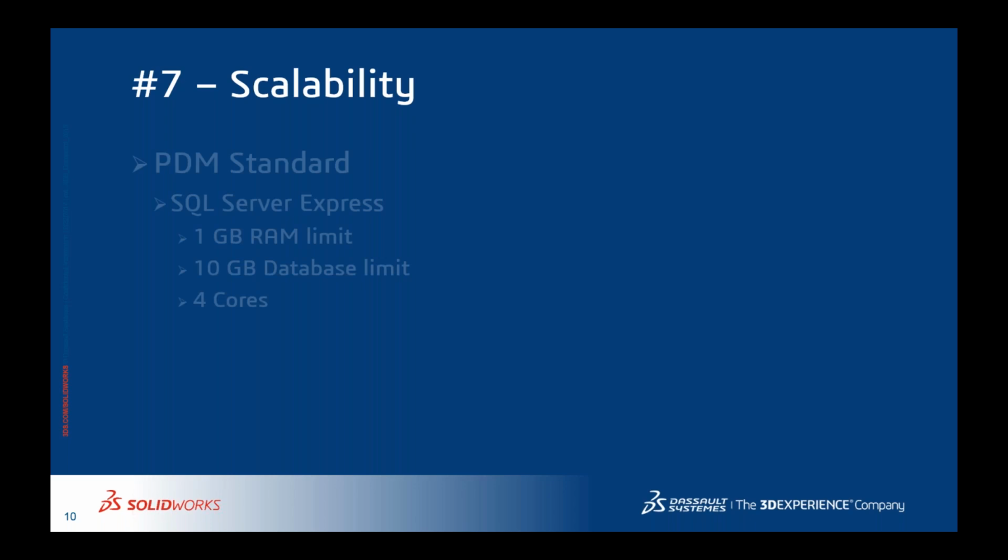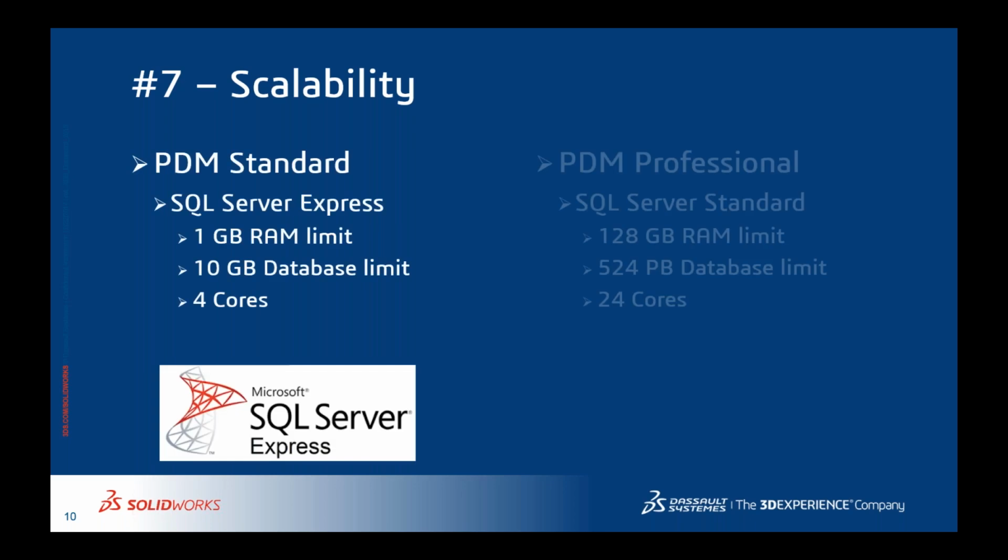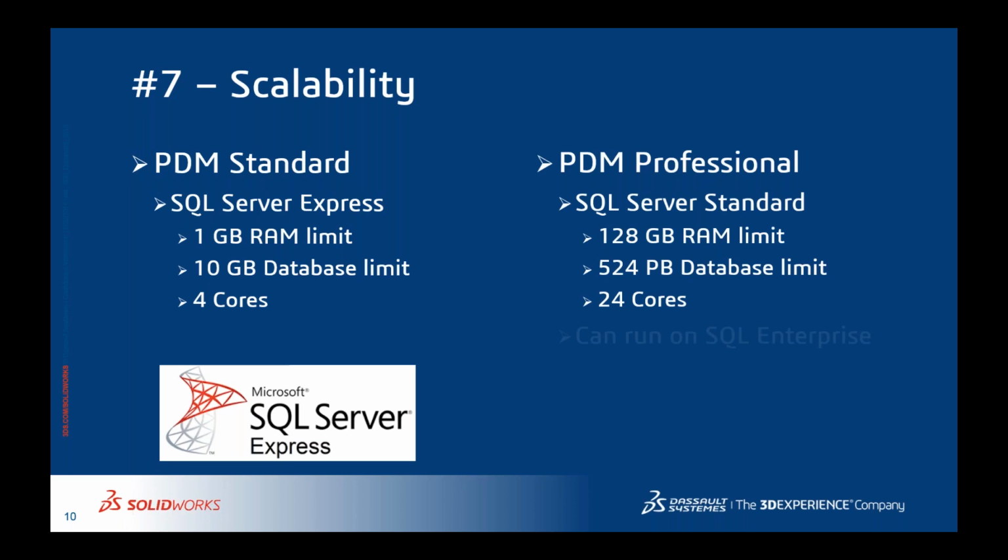So number 7 is scalability. With PDM Standard, as I mentioned, we've built it on top of SQL, but it's the SQL Express version, and so there are some inherent limits to the SQL Express server, specific to the amount of RAM it can reference, the size of the database, and the processor it can access on the server. With PDM Professional, we are building this on top of SQL Server Standard.